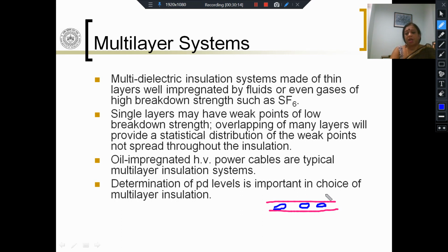They are everywhere. Now, when you apply an electric field across this, these gaps, these voids, will contain materials with lower breakdown strength, and they will break down. When these gaps discharge, this can cause ionization and collision, and by processes which I will take up later, the entire dielectric material can break down. Even if it doesn't break down, you will not be able to apply very high electric stresses across this material as you might across a section which does not have any voids.